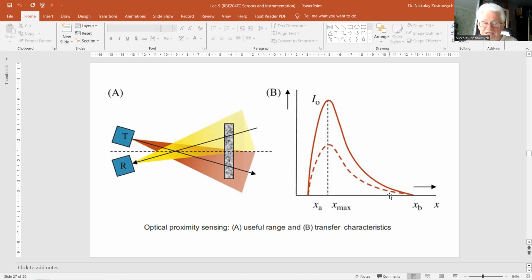The contact-free distance sensors discussed here are simple and cheap, principally due to the analog nature of the reflection measurement. A very high resolution, down to 0.01 micrometer, can be obtained. However, the accuracy is low, because since the output is an intensity signal, intensity variations due to other causes will be taken as a displacement.